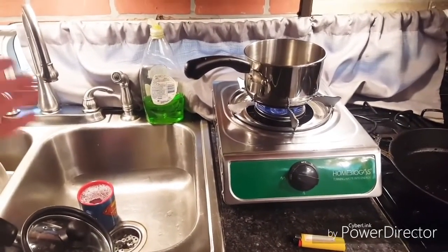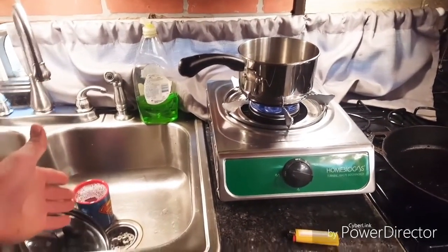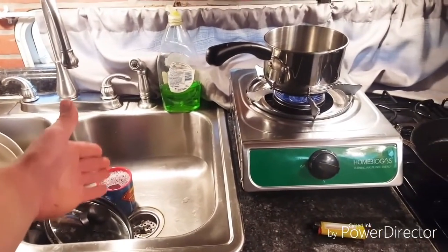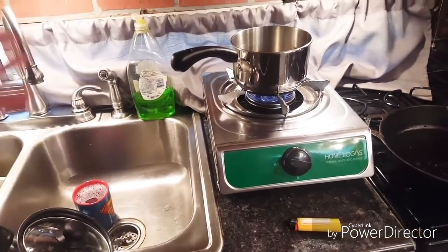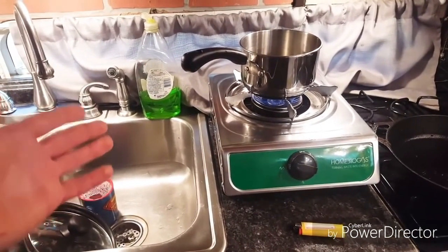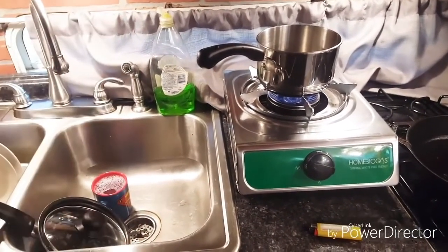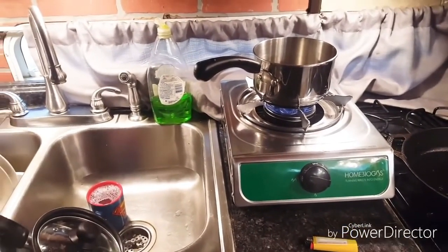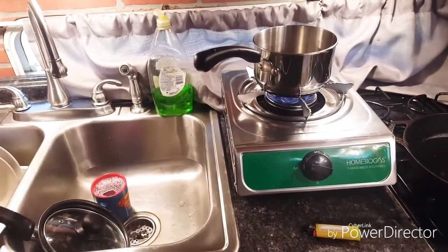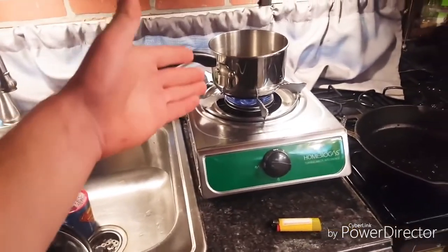You have the initial use of the water out of the tap into like the sink here, washing dishes, and then it goes down to the gray water tank. It's the first time, and then it gets pulled back up and it gets used in the toilet to flush again for the second time, and then it goes out to the biodigester and it aids in a process of making methane, which you could argue is a 3rd time, and then it is turned into methane to come in here to be cooked with.